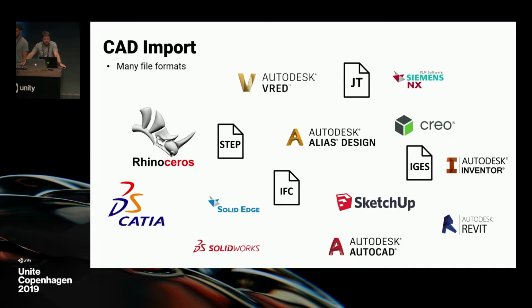In the data preparation process, the first and most important step is the CAD import. It is essential to retrieve the most accurate definition of the model to limit the complexity of the data processing. We handle a large amount of CAD file formats. Some of them are standard, but mainly they come from proprietary formats designed by CAD software editors.